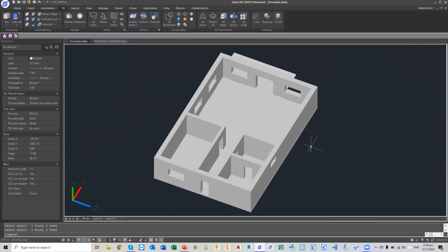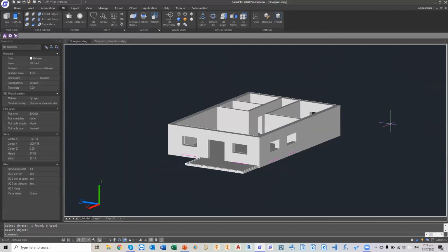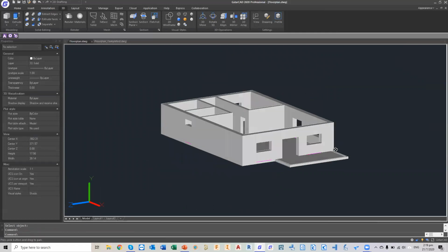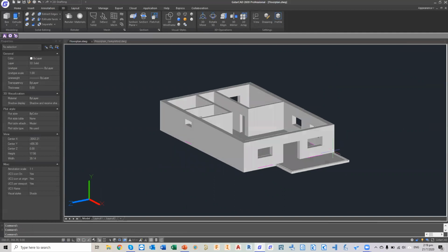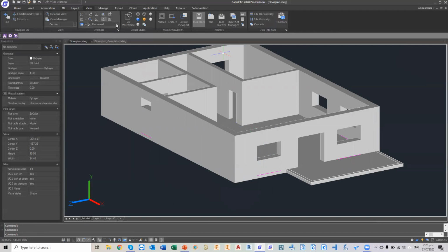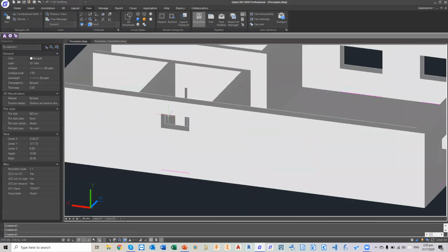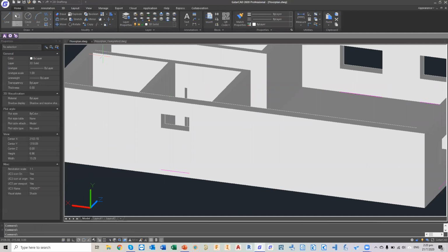And then press enter. Okay, so now you have the opening for your windows created over here. After you have the opening, you have to create the shape of the window inside the opening. So now I will change my view to front, and then I need to sketch out the outline of my small window here. So I go to rectangle, I'm going to create one rectangle here.